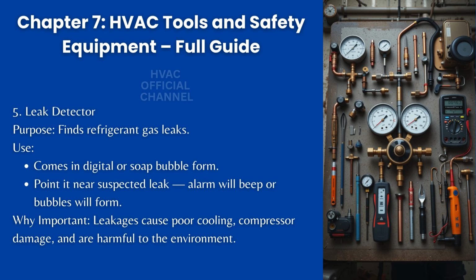5. Leak detector. Purpose: finds refrigerant gas leaks. Use: comes in digital or soap bubble form. Point it near suspected leak. Alarm will beep or bubbles will form. Why important? Leakages cause poor cooling, compressor damage, and are harmful to the environment.